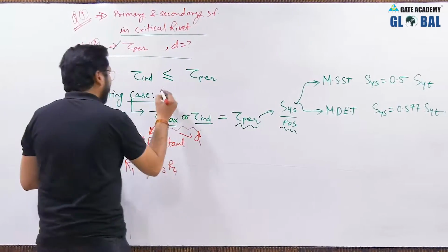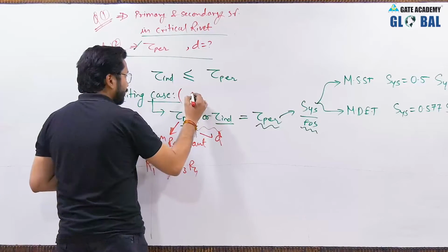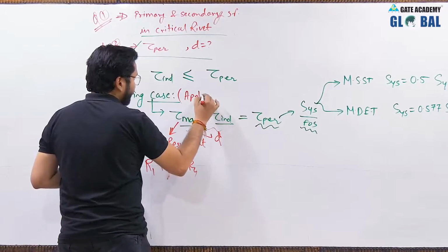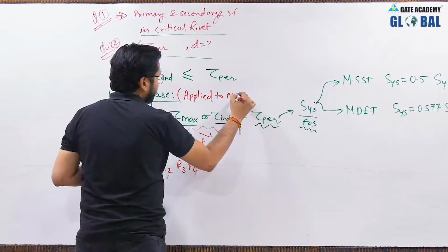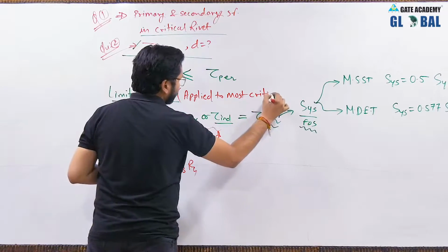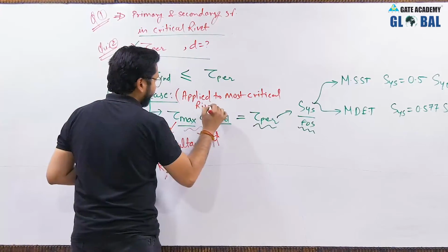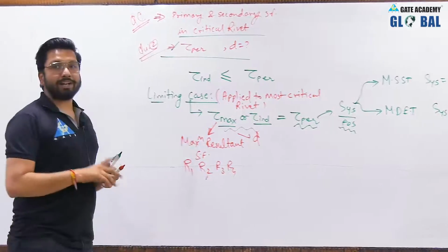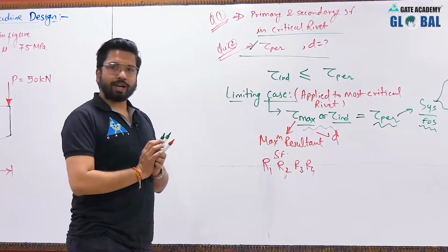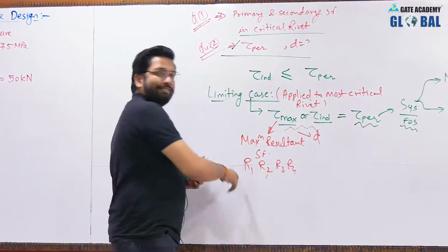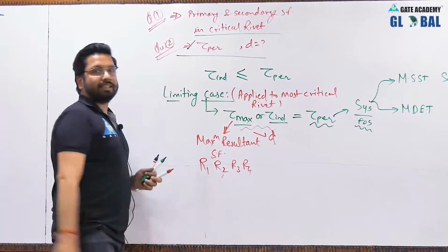This limiting case will be applied to the most critical rivet. So for designing we will be using the greatest value among these.